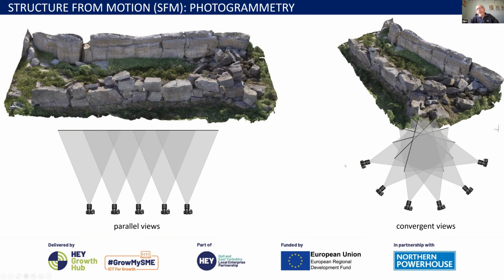But there's another technique out there that will gain a lot more credence, a lot more credibility, and we will see its use grow, which is photogrammetry, where you use a really good digital SLR camera to take a series of pictures, either in parallel or in an arc, where software then looks at these images, can see that they're taken from different angles, and is able to create the geometry from that. It creates a point cloud, it wraps texture to it, it then creates a polygon mesh that represents the surfaces that it's seen.